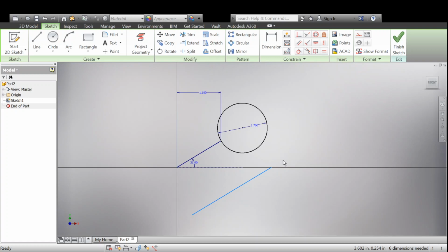Let's see what else for today. I wanted to just try and get through some features. So circle is there. Now that was a center point circle. Here's what I'd like you to do next. Grab the line feature, please. Choose line and make a triangle. Does not matter what size. All I care is that the ends all match up. Make sure that the triangle is closed. So when you go back to your starting point of the triangle, make sure it turns green before you click.